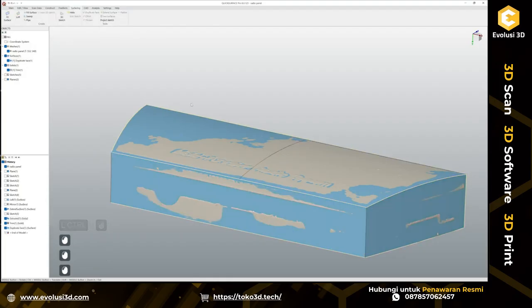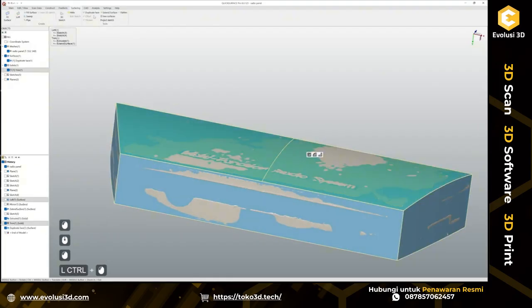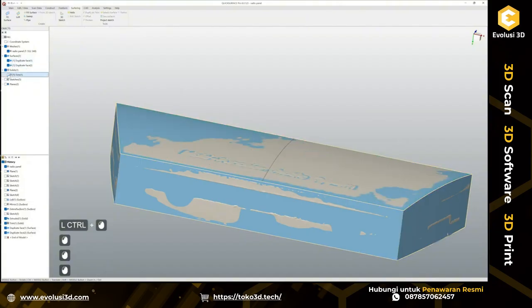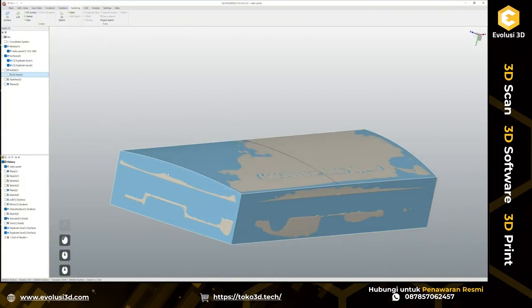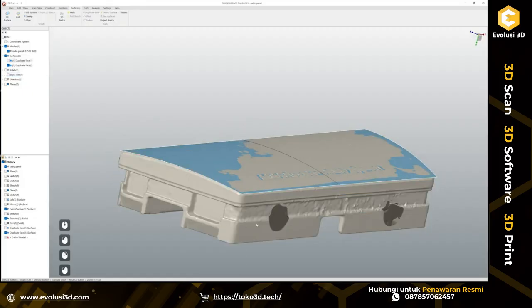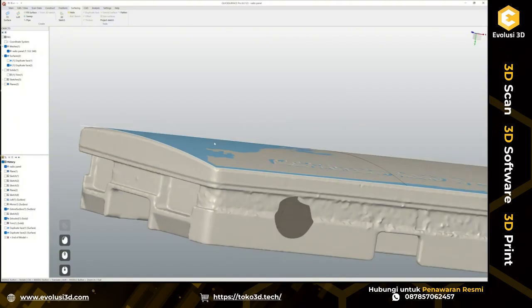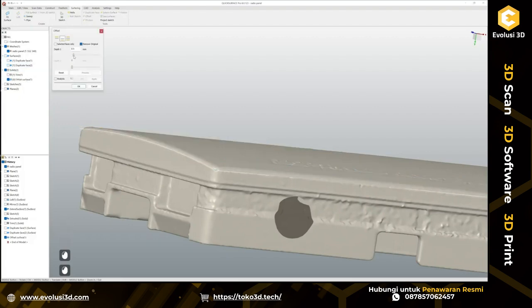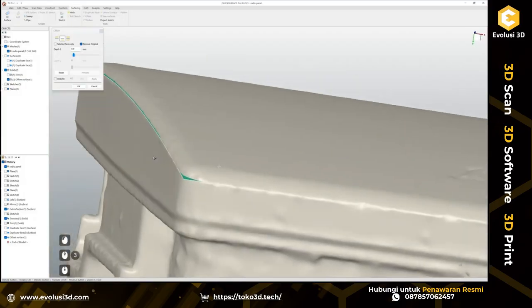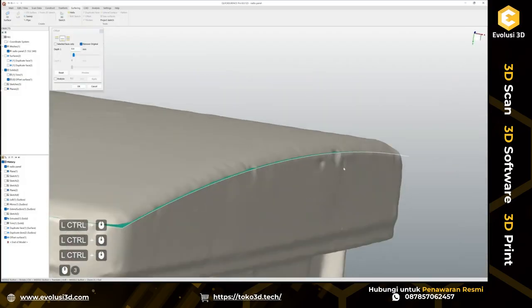Let's duplicate these surfaces and let's duplicate this one. Let's hide solid. So for now I'm going to hide side surfaces, and I want to offset this one approximately to this sharper edge, so it's somewhere, looks like here, maybe 0.7.